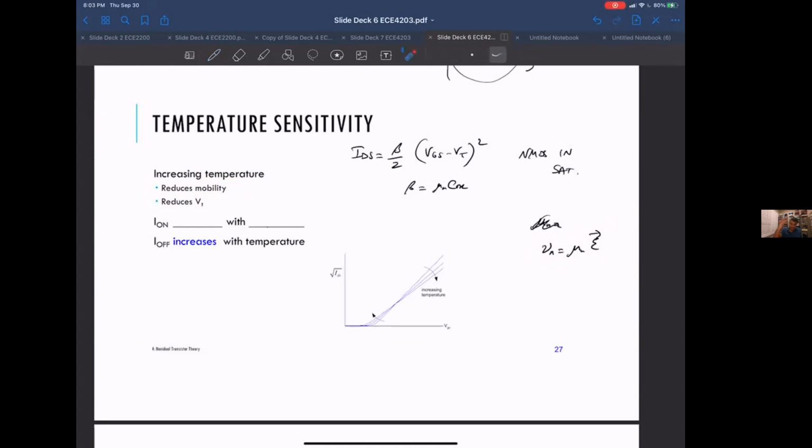If you take a semiconductor class, you'll see that it does all sorts of funky things, but most temperatures we're dealing with are, say, minus 20 C to 85 degrees C, typically. This is where most of our chips live. So in this range, mobility goes down with temperature.